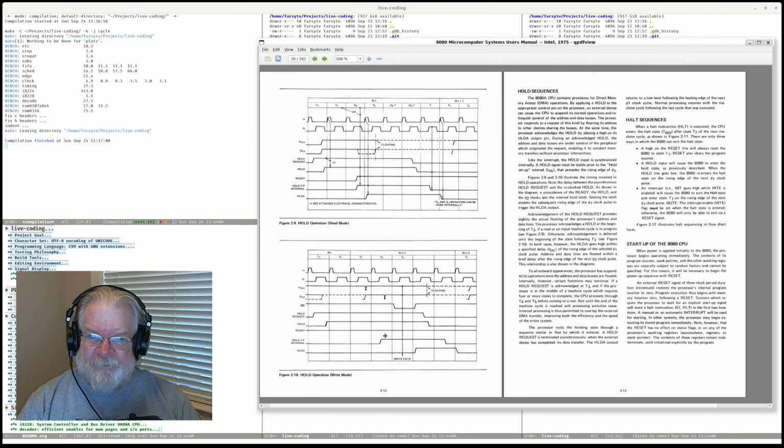Now, we already have a T-state for take data from temp and put it in a register. In this case, I don't believe that data goes into temp. It would say it here, move immediate M into data. This moves B2 into temp, and this moves temp into data bus. Okay, this is move immediate M data. So this uses temp, and this goes directly to the register. This is fine.